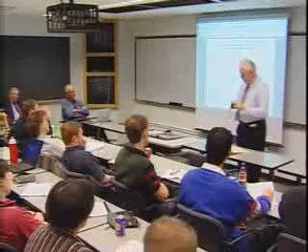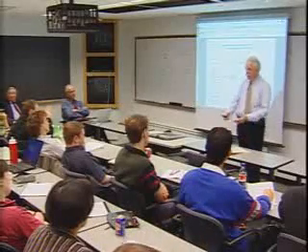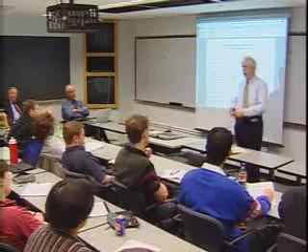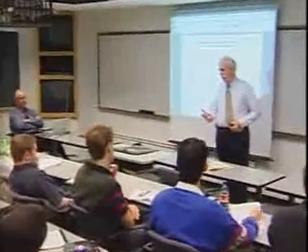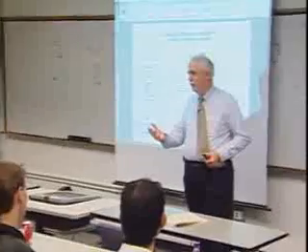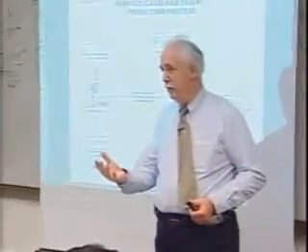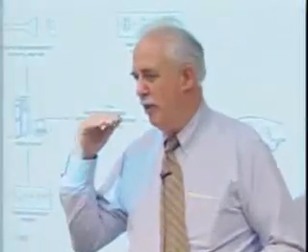The structures guys like to make things nice and flat or cylindrical, and the flow is continuous radius of curvature type phenomena. And that difference is very, very important, particularly for boundary layer transition. So we did fair the geometry to keep the boundary layer transition essentially 2 orders of magnitude lower than it might have been. But overall, I'd say predominantly it is aerodynamics, and we tried to calculate the heating to the configuration that we had.